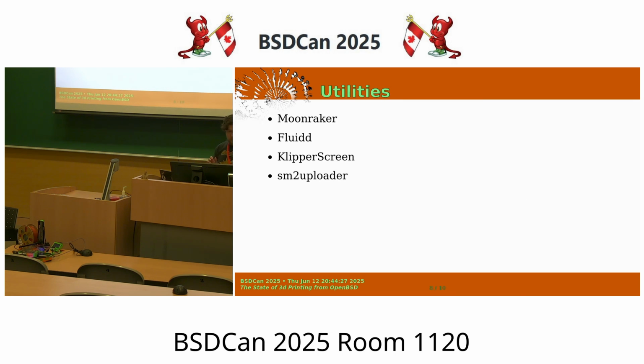once we have that, I wanted to talk about the thing that I found with the Klipper itself, is that because it runs so minimal stuff on the microcontroller, and most of it is written in Python and running on the computer, people have written a lot of plugins for it and things like that. Running on the Raspberry Pi over there is Moonraker, which is a web API, REST API sort of interface that talks to Klipper, and then different things can talk to it to get status from the printer and to send prints to it and stuff.